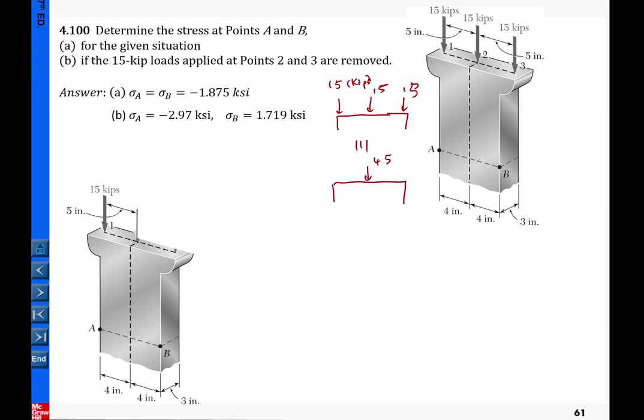So this is our chapter 1, chapter 2, the axial loading case. So basically the stress equals the magnitude of P divided by A. The magnitude here is 3P. Okay. So that is 45 times 10 to the 3 pounds divided by whatever the area. The area, for example, here it didn't show. Okay, area here is 8 times 3 inch square. Okay, so that is for A.